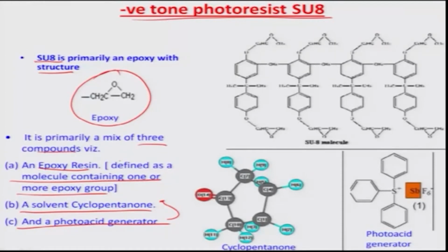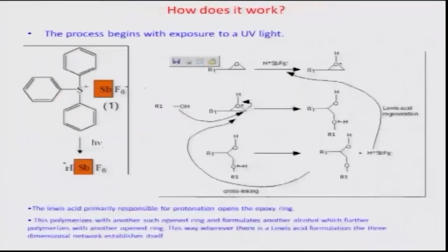the solvent. So once this coating is done, the photoacid generator can be photo exposed to furnish positive hydrogen ions or protons, and the protons can play around with this epoxy ring right here by opening it, so that you could actually have a cross bonding structure. So let us look at what happens here. For example, this is an epoxy ring with an R group.